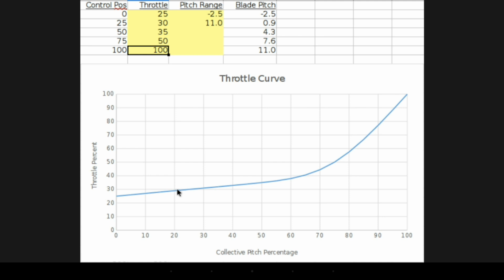And so when the throttle reaches that point, the governor takes over and changes the speed to what the governor is set at over the next 10 seconds. So it ramps it up to rated head speed. And from that point, the governor just follows the throttle curve. And the reason this is important with piston engine governors, in just about all flybarless units and standalone governors for piston engines, is that they use the throttle curve for feed forward to provide a quicker throttle response.